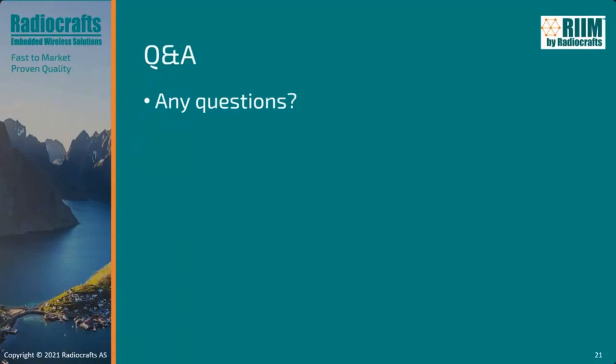Of course, a PCB antenna at 868 will be larger than at 2.4. Typically it goes from a 2.7 centimeter wire up to 8.2 centimeters, I believe. So it all depends again on the space requirements of your product. But please contact our support, Magnus, and you will be in contact with me and Omar, and we can look into the case specifically together with you.